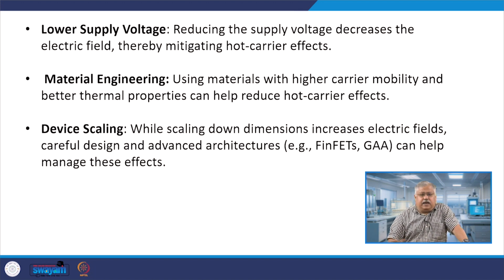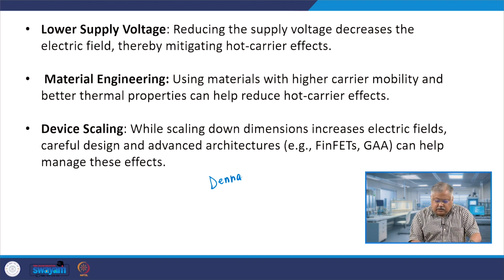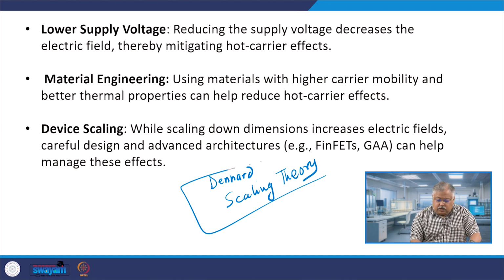Another good way, and this is where we will be delving more and more as we move ahead in the lecture series, is device scaling. If you are interested, you can work out something known as the Dennard scaling theory. If you look at this Dennard scaling theory, you will see that you lower the channel dimensions, but you lower the VDD, the power supply, as well. Once you do that, you end up having a better scaling.